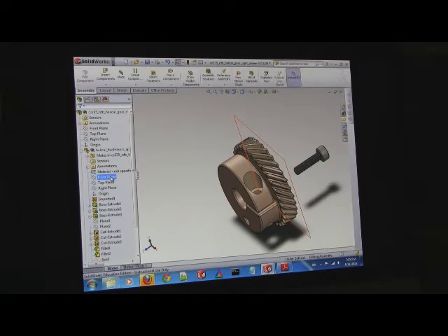If you guys press mate and it doesn't do it, it's because your gear is still fixed, probably. Yeah, see, it says it's fixed. So you right click, hit float. Now it moves around. And now that shows you the planes. So you press that and then control and that, and then this is the mate button. And then you hit the green check mark. In here to select more stuff, you use the plus sign, top, top, and now you do the right.